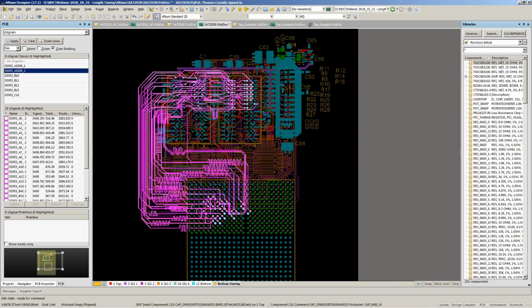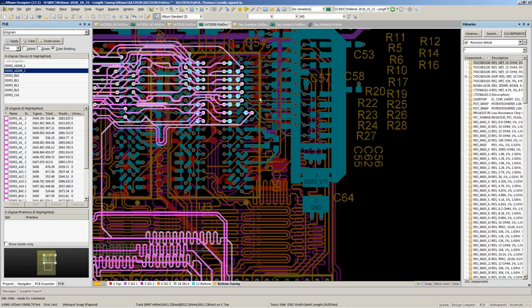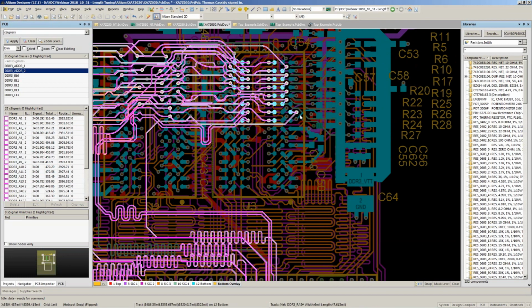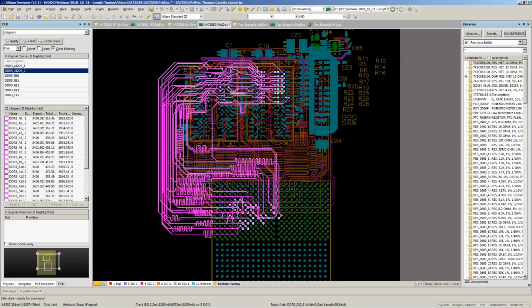And once again, as you see here, I'm terminating at the last chip. The termination resistors are not included in these calculations. So a very nice tool if you're doing some DDR3, and they also have a version for USB to help you with some of the more specifics of dealing with USB when you're going through their termination and protective chips.